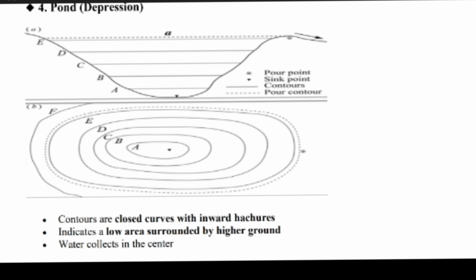This one is a pond or depression. This is called a pond. It will show closing circuits, with inner hachures, and it is a low area surrounded by high ground. Water is collected at the center portion of it.